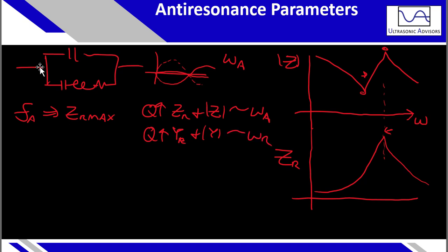But we want to make sure that we're not leaving it open to interpretation about what the actual value we should be analyzing is. We have to just simply calculate the real impedance, and that is done using impedance magnitude multiplied by sine of the phase of impedance. And that will allow you to calculate this value.